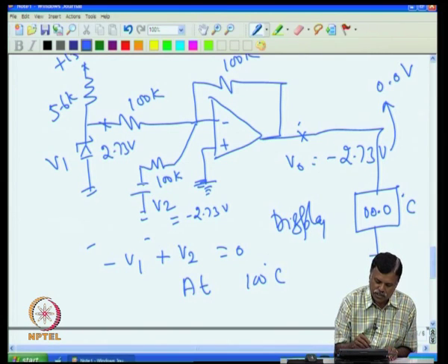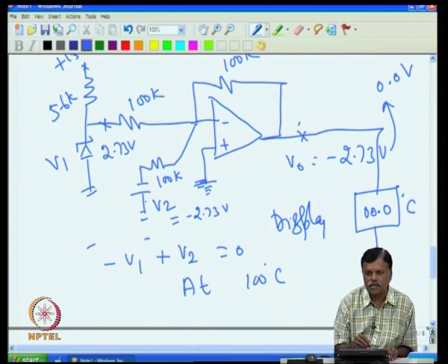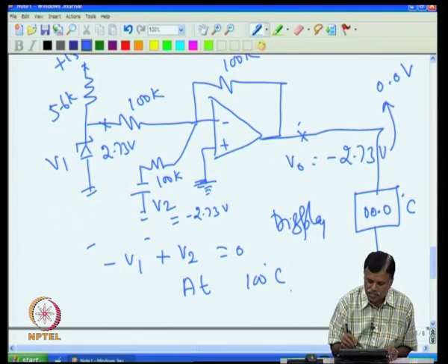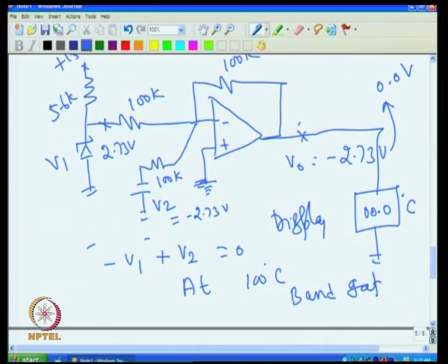Even though we are not putting this Zener inside the oven where we are measuring the temperature, with ambient temperature this voltage should not change. So, we have to have a stable Zener. You can get it in the band gap Zeners, which are very stable. For example, the classical one is LM336, that gives you 30 ppm stability against temperature.